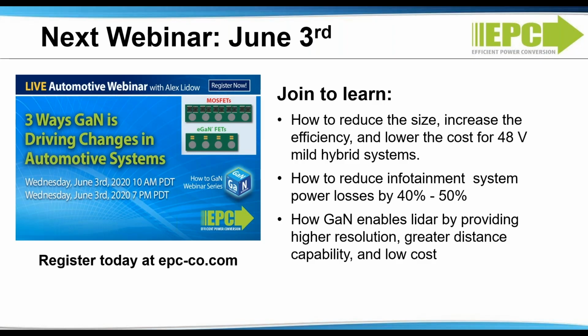What feature of the switch capacitor converter is responsible for its low power density capability? I think the real answer is that there are a lot more components in a switch capacitor. You've got about twice the number of transistors and twice the number of overall components in a 300 watt switch cap 48 to 12 than you do in a buck converter. When you add all the peripheral stuff, it comes out to be about a third of the power density. As you scale up in power, of course, these switch caps just become too large. They take over the whole board.